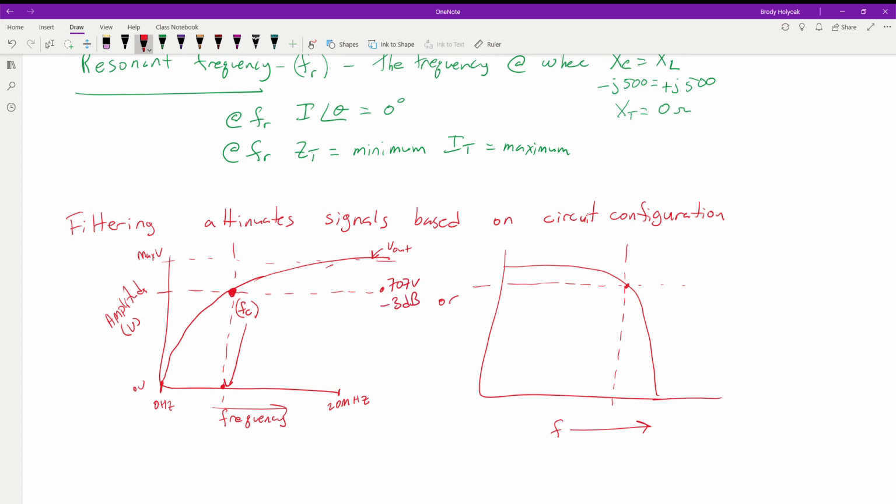Now that we've created this, we have this critical frequency. So if we go, for example, in this first circuit, this first waveform, if we go lower, anything in the low end is going to attenuate our signal heavily. No matter what we put in, it's going to drop it by 0.707 or less. Especially when we're starting out, we're going to get almost nothing, and then it's going to climb up a little bit and then flatline. So this area over here is our reject area.